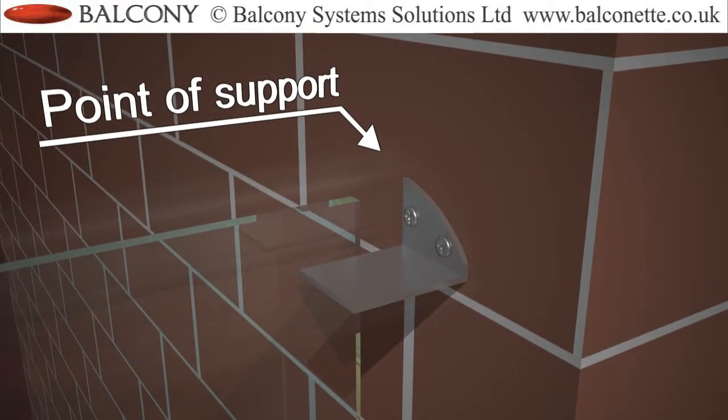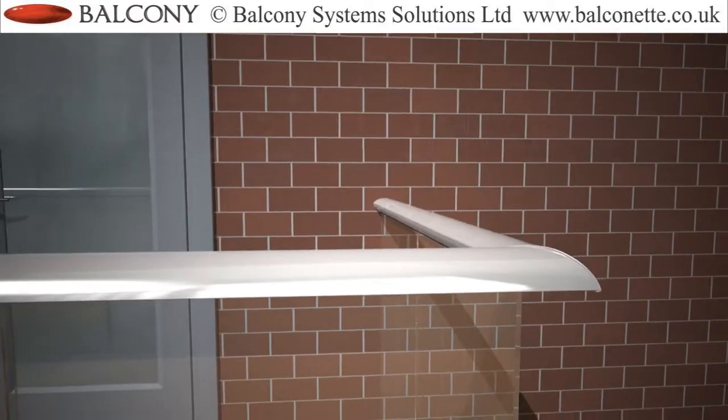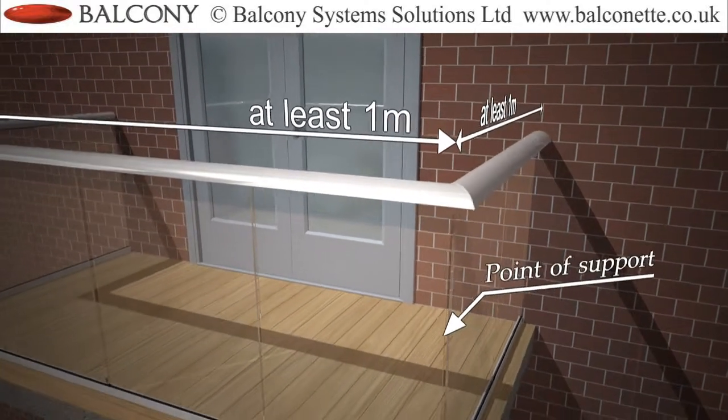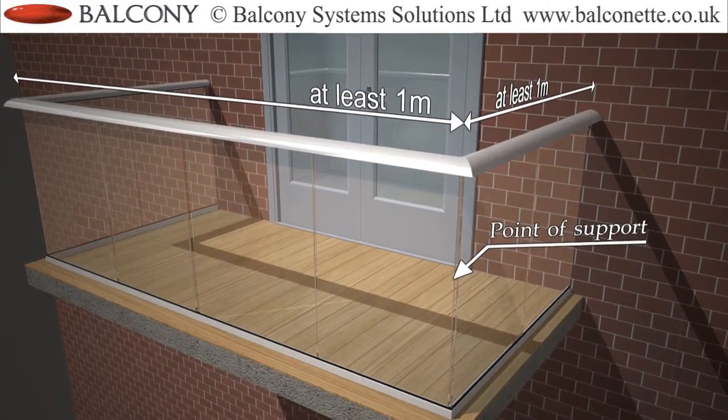Due to the way the system works and the way the glass is bonded to the rails, a corner of 90 degrees where the sides are at least 1 meter long is also considered a point of support, and therefore the maximum span rule applies to such a corner.